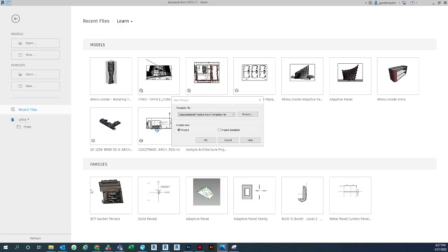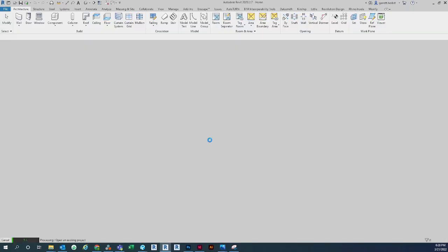Hey class! So today we will be doing something a little more exciting in Rhino.Inside. We will be creating from scratch a tower, a rotating parametric tower, and all of it will be generated in Rhino.Inside. We'll be generating the levels within Revit, the floor slabs, the structure, and quasi the mass. We'll work with the mass a little bit more later on in another assignment, but for today, we'll be creating those components. So we'll get started by opening our Revit template.